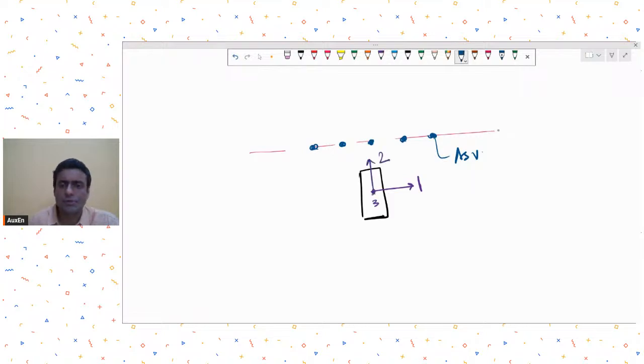Let's say you are using SAFE software. So this is for V23 shear that I am checking. When you find out, this is your ASV, and then you are going to distribute it. So the next set of bars come like this, and this becomes your SV.